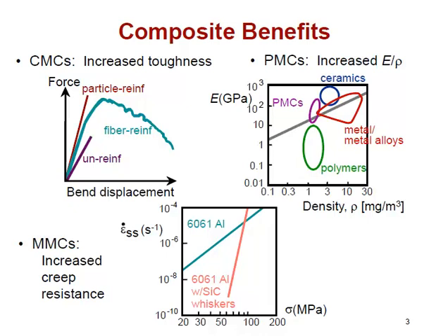This is a single crystal elongated reinforcer, basically an anisotropic crystal with a very high aspect ratio added to the aluminum matrix. This is distinct from a second phase precipitating out during heat treatment. This is a deliberate addition during processing, very easy to do with powder metallurgy. And you can see that in this case, we have strain rate plotted on the y-axis and stress on the x-axis, and the difference in slope and position is indicating an increase in creep resistance.